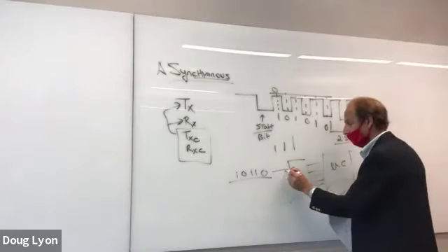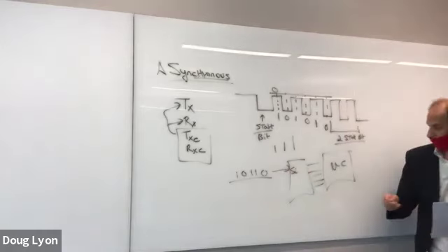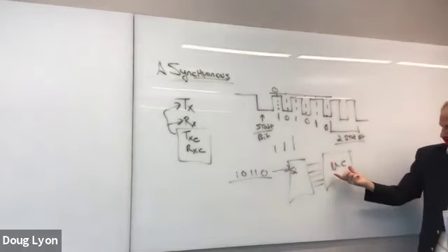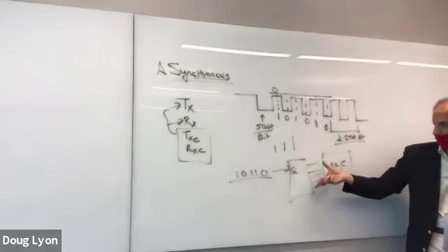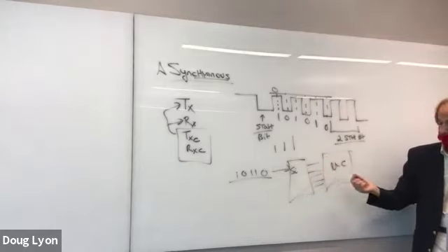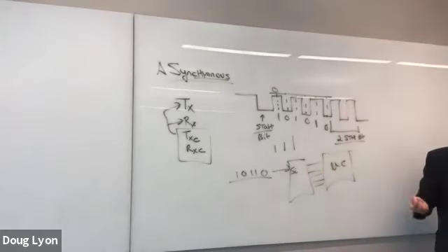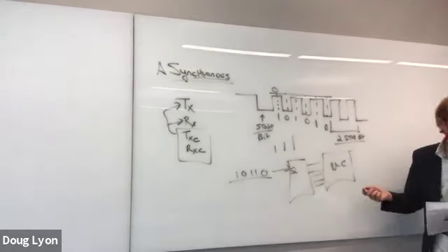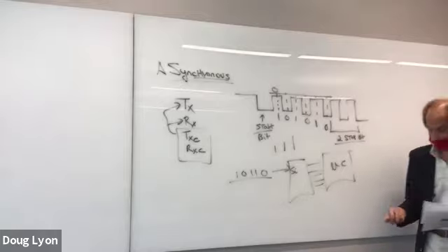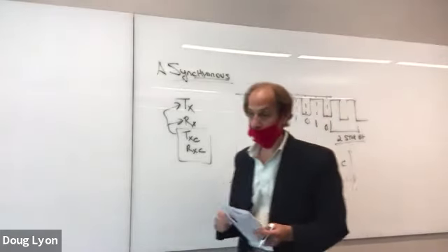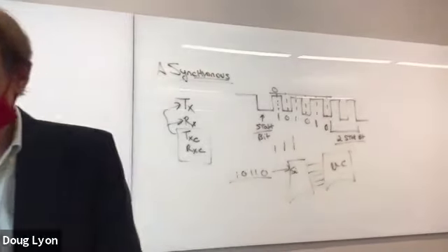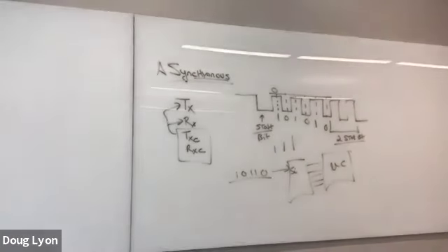So this goes in marching along 1 bit at a time. So it comes out in parallel, and the microcontroller is signaled that these bits are ready, and it takes those bits and pushes them into a stack, or throws them into an array, or does whatever it's doing with serial data. And you see this all the time when you open up the serial monitor on your Arduino IDE. Right? That's a critical task.